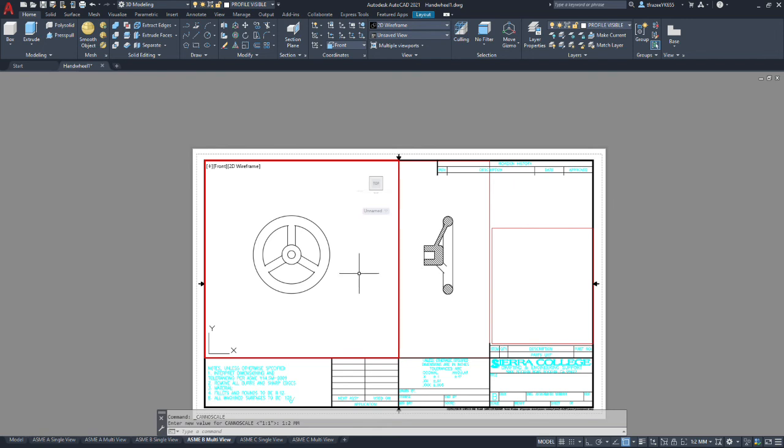Okay, so now we've done step 26. We've created custom scales in 26A. And then we're going to position the front view. Yeah, it looks pretty well centered. We don't want it exactly centered because we want it actually really centered between here and here. So let's lower it just a tad. That way this view is also centered in the space.